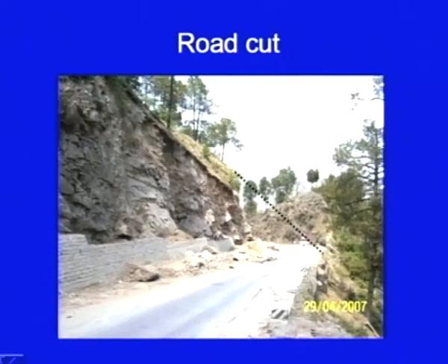We have constructed a road here, and this particular material, now you can see, we have removed from the side. So actually this material, this soil mass or the rock mass, was being supported by the material which we have excavated. So there will be a tendency of this particular geological media, whether it is soil or rock, to try to slide in this direction because of gravity.